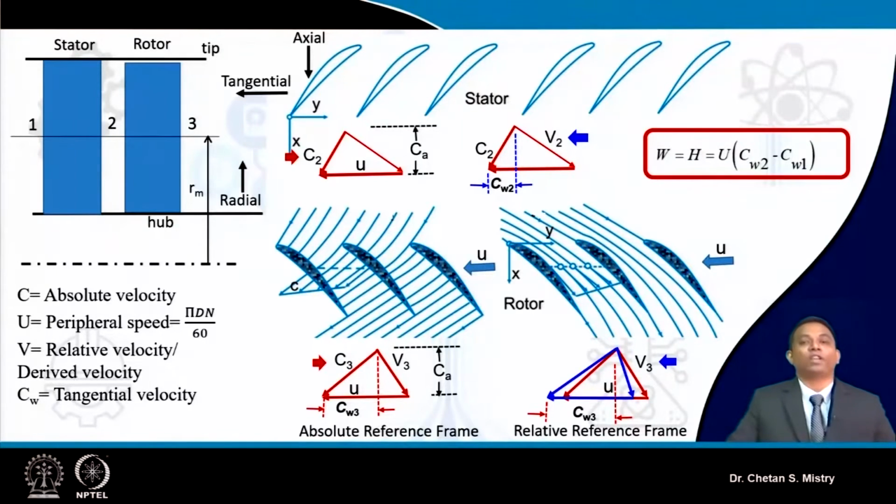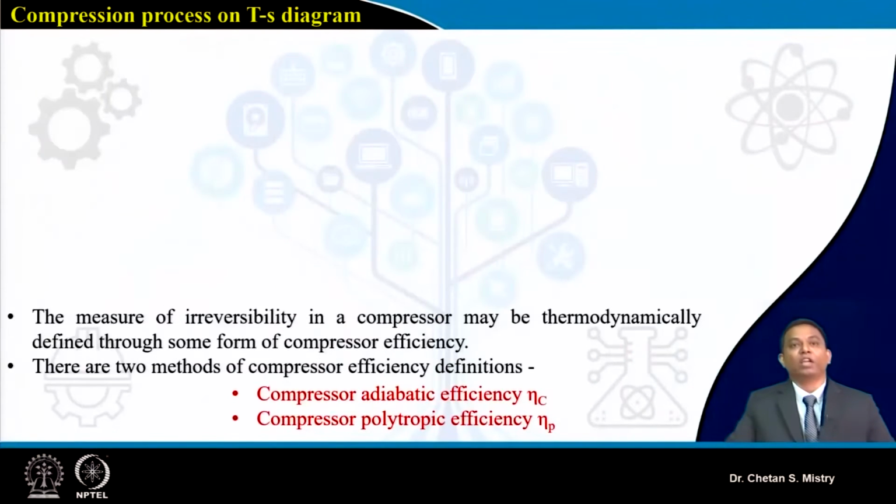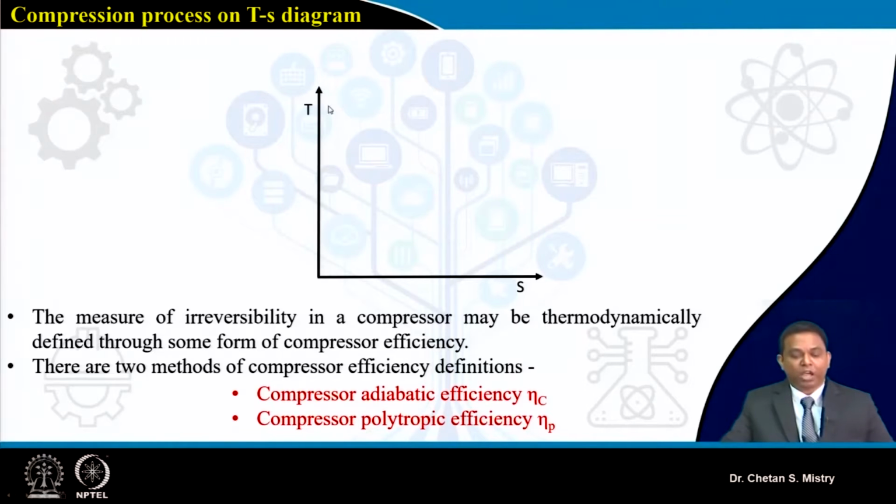Now what we know so far represents my aerodynamic configuration. Now let's try to understand this compression process using the thermodynamic aspect. Here, I represent my compression process on a TS diagram. I have my entry pressure, P01, and my exit pressure, which I am writing as P03.